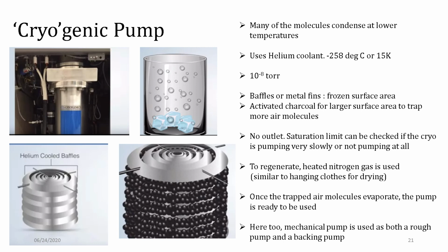The saturation limit can literally kill the working of a cryo pump, which means if all of these air molecules condense on top of the baffle or fin, when it cannot trap any more air molecules, it cannot work as efficiently as it used to. So it needs to be dried up, it needs to be evaporated, then the pump is ready to be used. What it actually does is molecules condense on these baffles or metal fins, thereby making the chamber quite sealed.